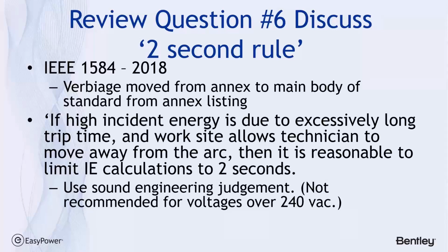On the other hand, I suggest if you're going to use the 2-second rule, apply that max limit, you wait to do so until after you've done coordination, because limiting the calculations to 2 seconds could interfere with misaligned coordinated devices. And it's something to play with if you don't understand the implications.